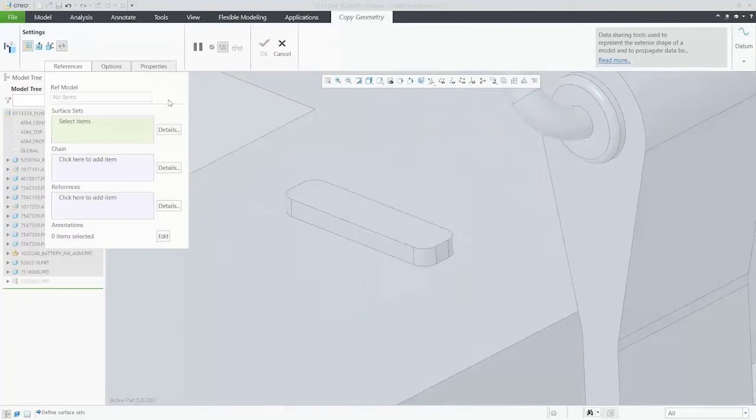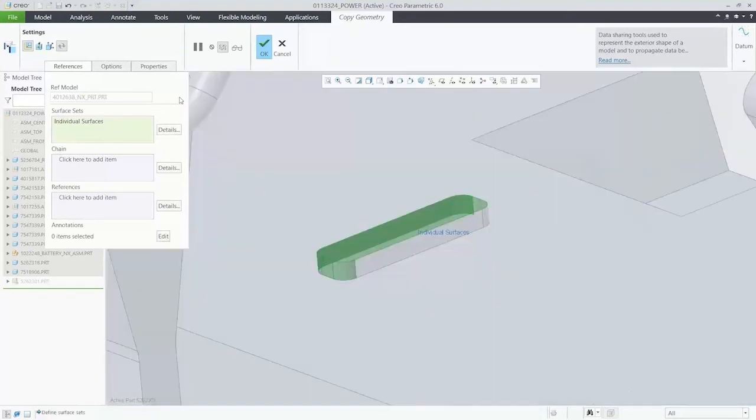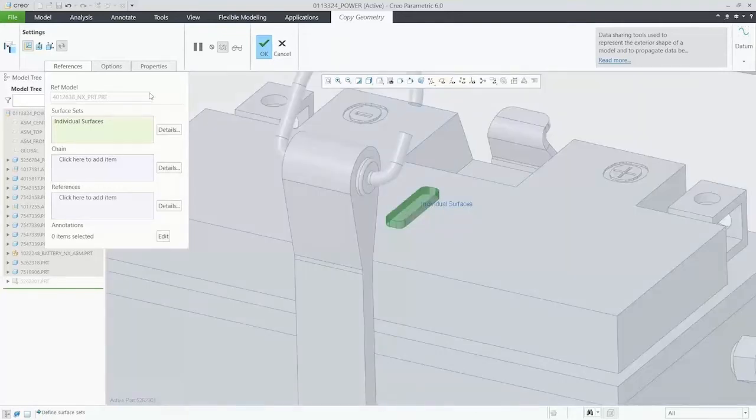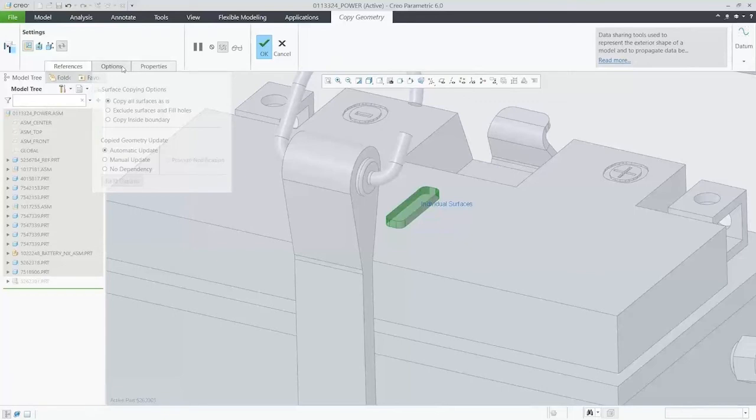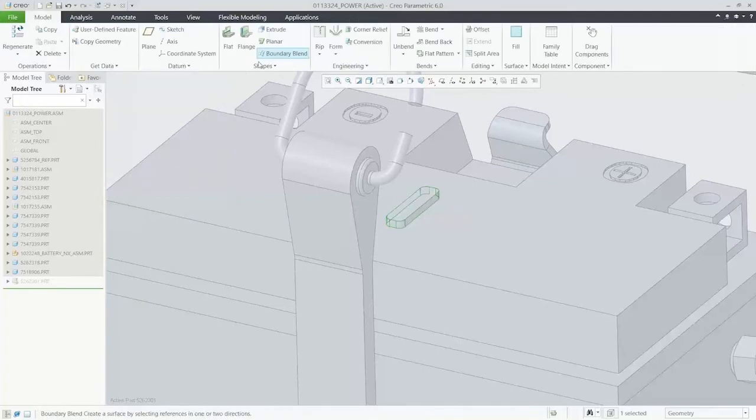This little tab that we have up here, we need to make sure that the hole is in the right spot. And things like this, maybe they get changed often, and you want to make sure that there's design intent behind it instead of just creating the cuts by the dimensions you think they're going to be. If you reference the surfaces, even though these surfaces are on the battery, you can reference them to make sure that cut is always going to be aligned and not redone or forgotten about later.